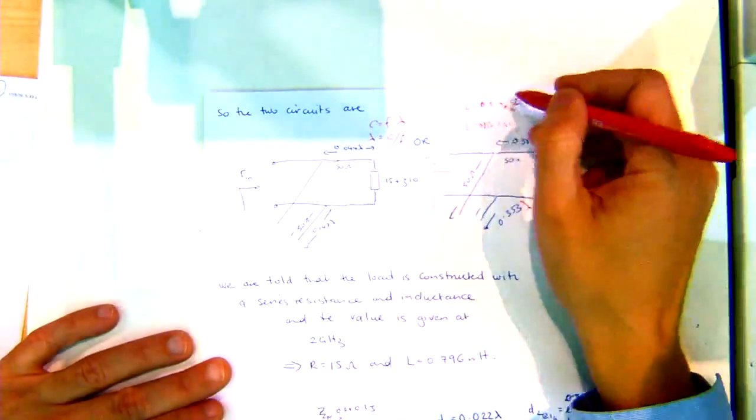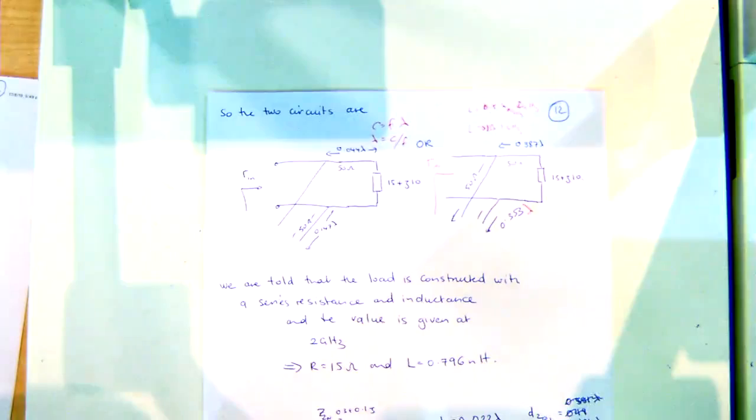Just in this calculation, what's happening that's different is that because you're at a different frequency, that piece of wire is no longer 1 lambda. It's half a lambda, right? And if you were at 4 gigahertz, it would be 2 lambda, right? That's all I'm saying.